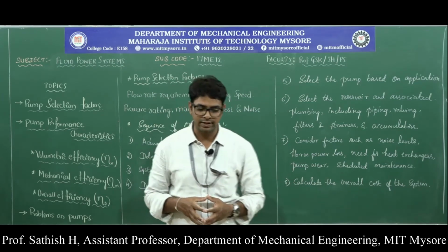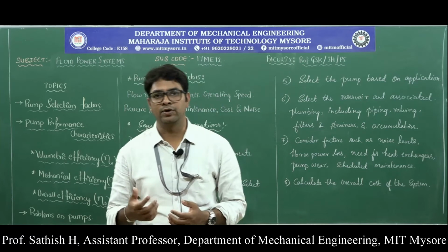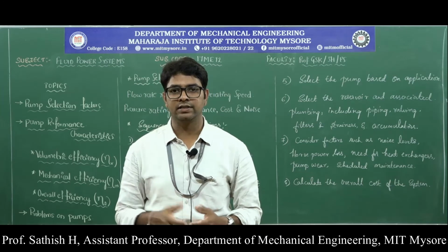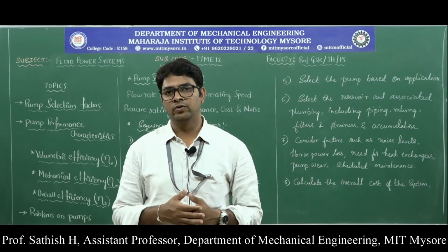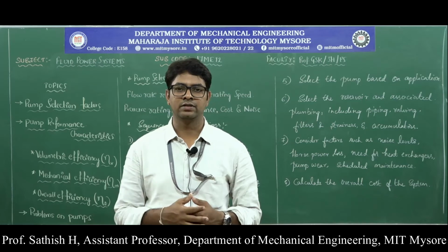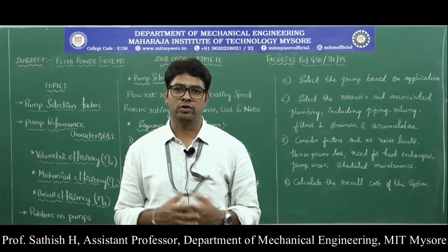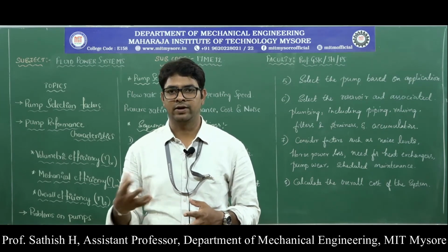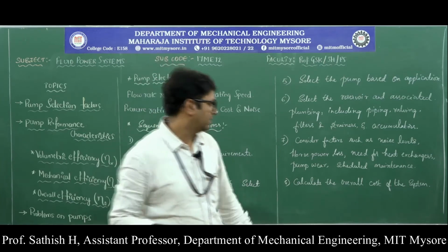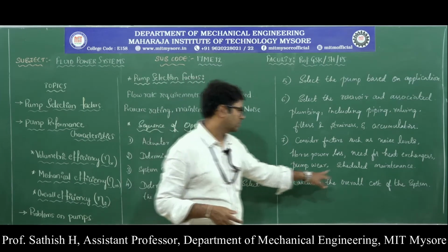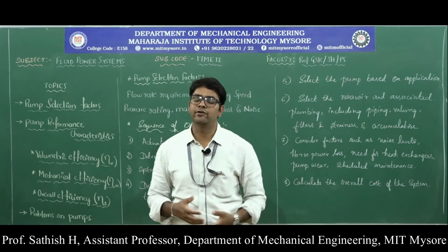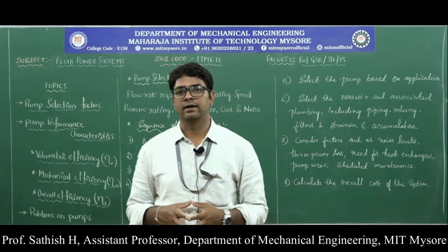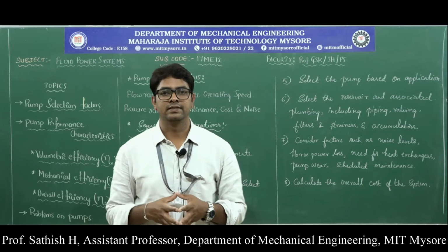And then heat exchangers. When the fluid is operating under pressure, it will undergo an increase in temperature as well. So in order to remove this heat from the hydraulic fluid from time to time, either within the reservoir or by providing external devices like a fan or a radiator, you can remove that, so we can decide that here. So, does our hydraulic system really need a heat exchanger? You have to decide that as a hydraulic fluid power system design engineer.